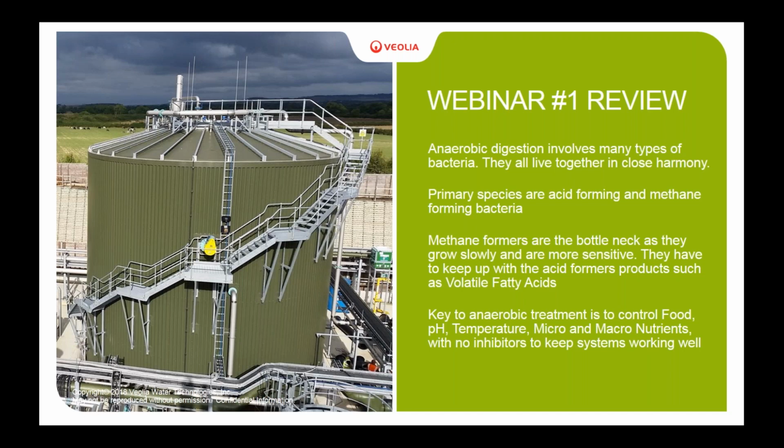And there are several keys to anaerobic treatment that you need to keep in line, including controlling the food, or controlling the COD load to the system, keeping the pH of the system around neutral, keeping the temperature in the mesophilic range, from approximately 90 to 100 degrees Fahrenheit, and giving the bacteria the nutrients that they need, not just the macronutrients of nitrogen and phosphorus, but also a micronutrient solution. And of course, try not to put any inhibitors, biocides, etc., down the drain that would prevent the biological system from doing its work.